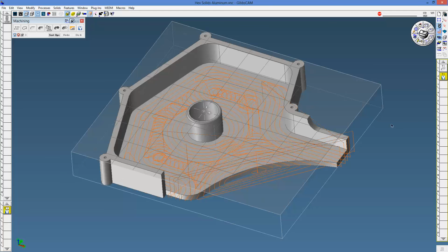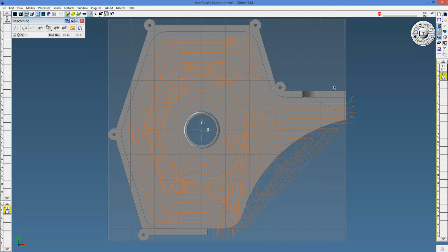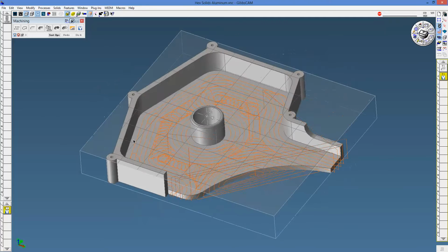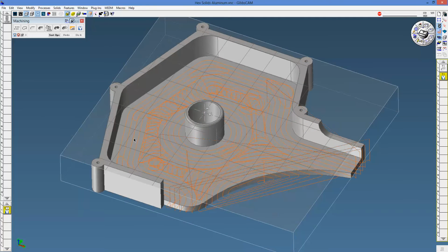Now, this is much more advanced than some other high-speed roughing algorithms that are available today, in that most of them use what's called 2D tool engagement. That is, they look at the tool, which is a circle, and they say, okay, of that tool, we only want this much angular engagement. So it's a 2D approximation of maintaining a load on a tool. This is actually monitoring the 3D removal rate. So it's quite a departure from that kind of philosophy.